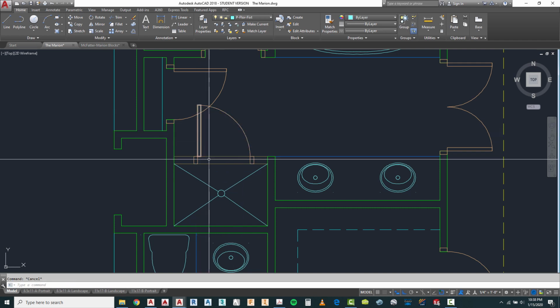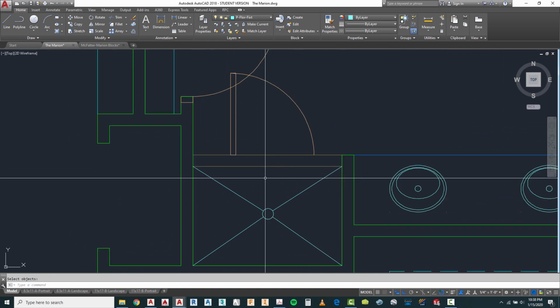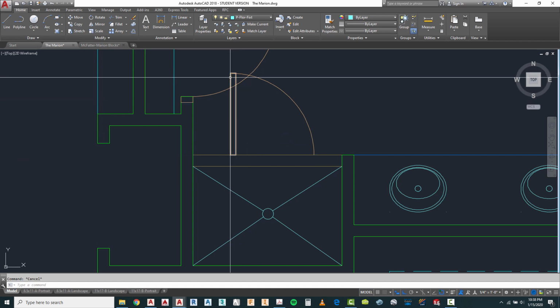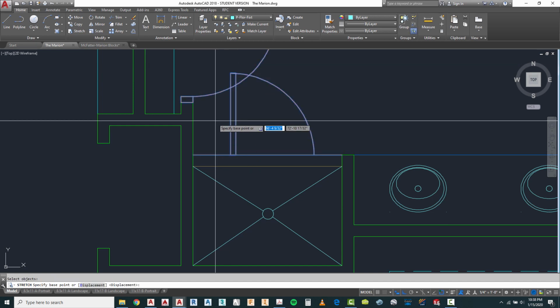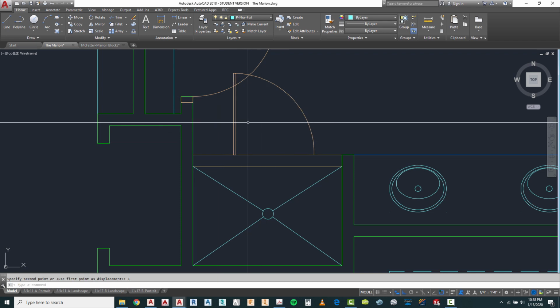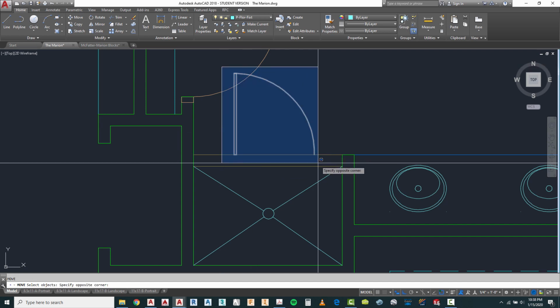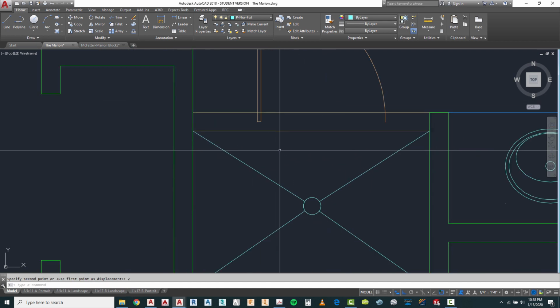And it's now individual elements. There are certain elements I do not want. I don't want that, and I don't want that located in there. Also, this represents a glass door, so it's way too thick. So I'm going to take that and bring it in about an additional inch, and now that's a little bit more than what I want. In addition to that, I'm going to bring it into the middle of my wall, which is about 2 inches into there.